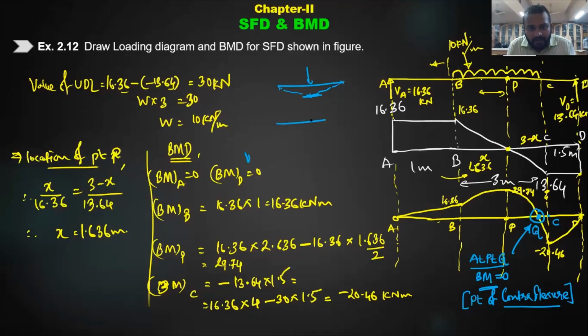But suppose if I have a beam like this and load is given like this, तो अभी तुम्हारा ये beam ऐसा bend होगा, right ना? So here at somewhere, ये जो beam था वो ऐसे downward bend हो रहा था, अभी upward. Sagging and hogging happen simultaneously. So at that point, the point where this sagging and hogging changes, the point is BMD 0, and that point is called as point of contraflexure.